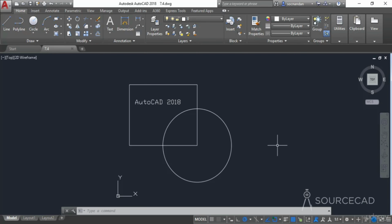So let's have a look at the boundary and wipeout tools. So I'll start with the boundary tool, and here we have the simple drawing. Now in this case, let's say that we want to find the area of this region. So obviously we can use the area tool, and that's an efficient way, but still we have an alternate way of doing that, and that's by creating the boundary.